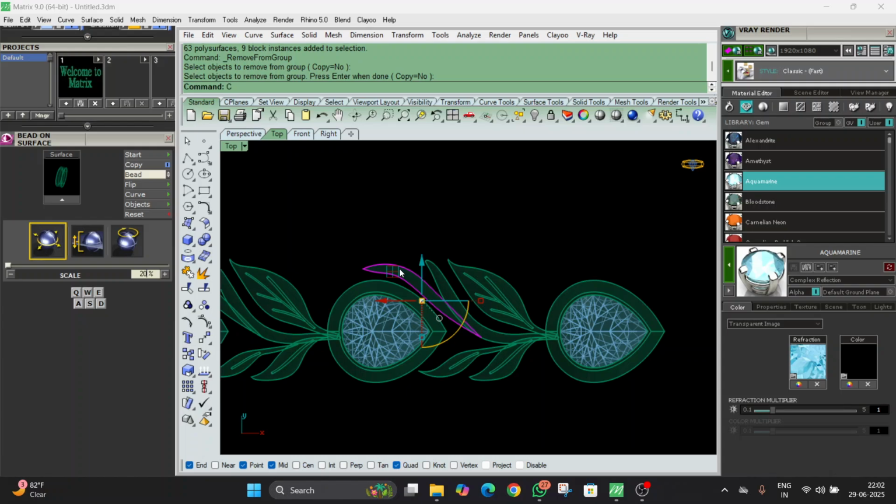We will cage edit it. I had used the shortcut command, but we can do it as cage edit. Enter. Selecting the object. Enter. Bounding box. And cplane. Enter. Enter. And we will select global.